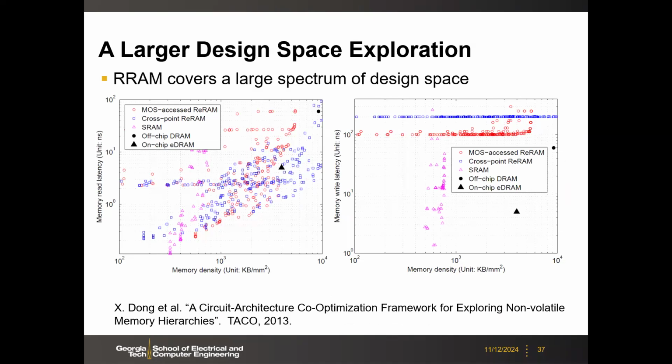So you see that here, in general, at the same technology node, the RRAM, of course, is smaller in cell size compared to the SRAM, right? SRAM is 6 transistors, RRAM is 1T1R, right? So that's why for the memory density, you see the pink, which is the SRAM baseline, is mostly here. And then the RRAM density will be better at the same technology node. I have to emphasize, because at that time, there's no 3 nanometer SRAM, right? At the same technology node, 32 nanometer.